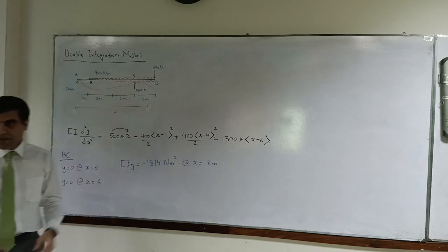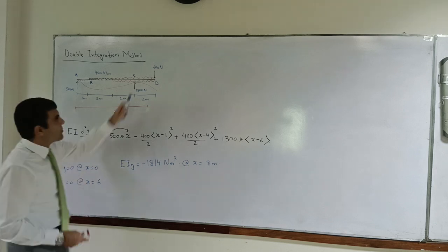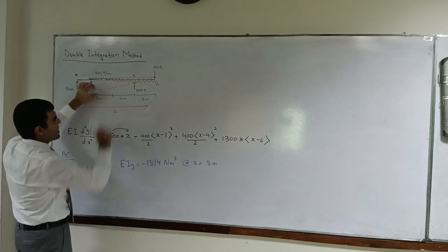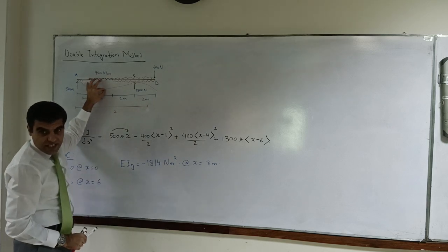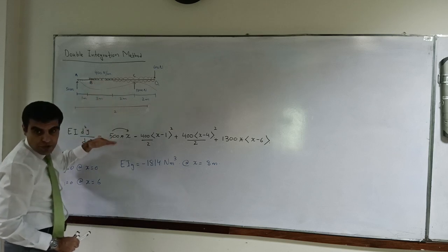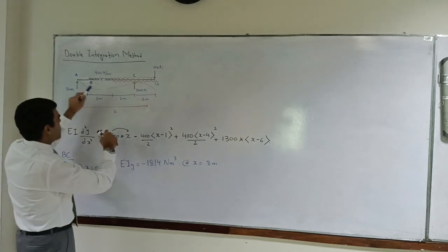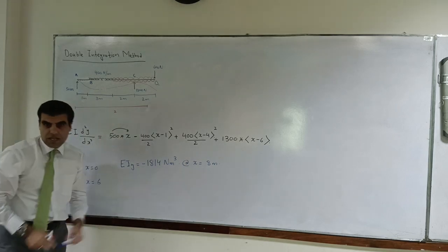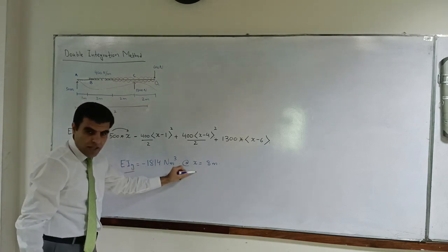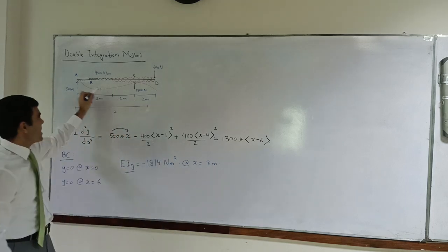Yes. And it depends on which load will cause more deflection. Because if this load is higher, what happens? This is trying to push up. This is trying to reduce this deflection, isn't it? Yes, sir. But if this load, which is over here, is higher, this is trying to push it down and increase this displacement. So we don't really know whether this one or this one is going to govern. So you can find out EIy at this one and compare it with the deflection in the middle.